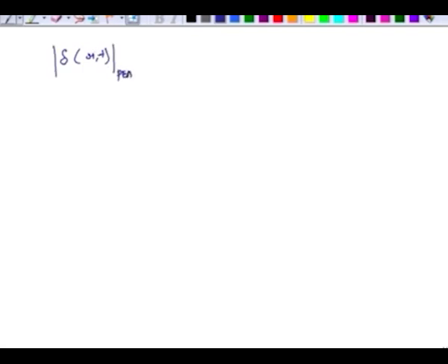The peak value of displacement is computed to be velocity peak, or the amplitude of that velocity, which was 4.42 times 10 to the power of minus 3 meters per second, and then I divide it by omega, which is 2 pi times 100 hertz. So, this works out to be 7.035 times 10 to the power of minus 6 meters, or 7 microns, a very small distance.